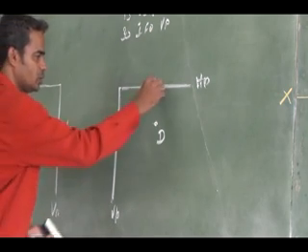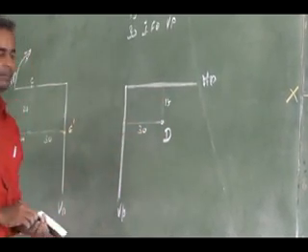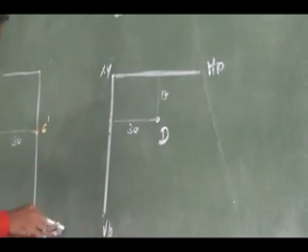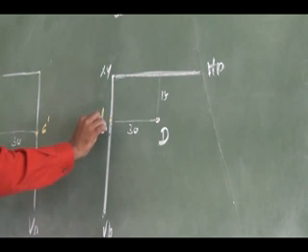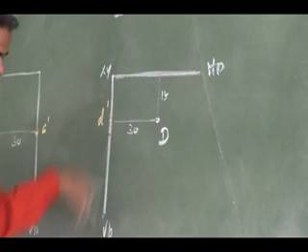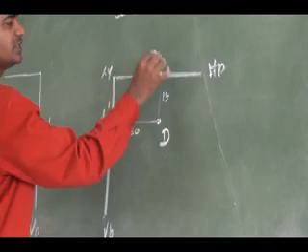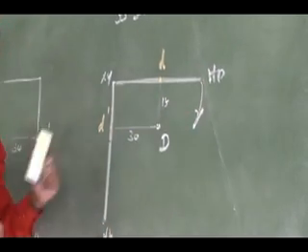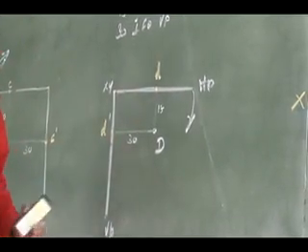Okay, make a note. This is 15. This is 30. So this is my XY. So this is the d dash. Whatever you obtain as a projection on the vertical plane is the front view. This is my small d. Now, by rotating the horizontal plane 90 degrees clockwise, both the views will fall below the reference line. Both d and d dash will be below the reference line.